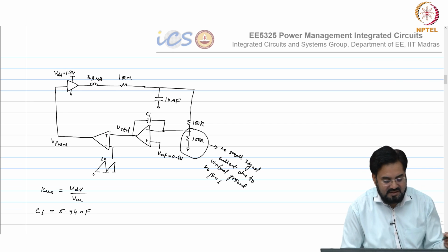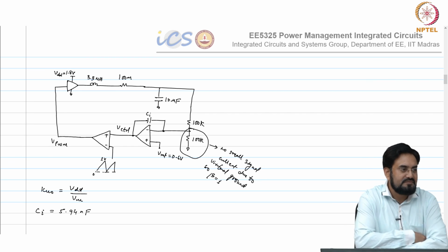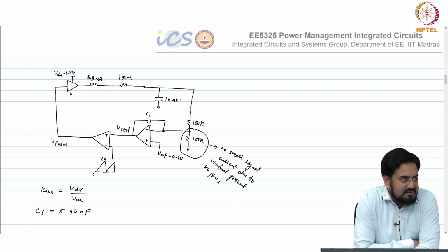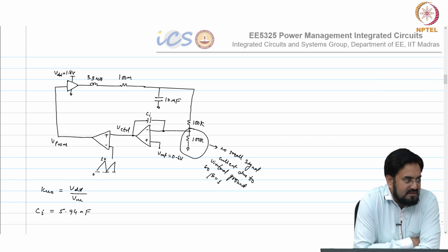So, when you go external, you usually choose mega ohm also, okay, but on chip you can do 1 mega ohm, we do actually, but tens of mega ohm is very unlikely, this will take a lot of area, okay.